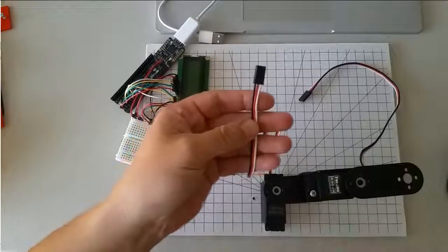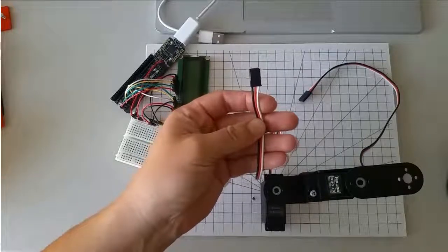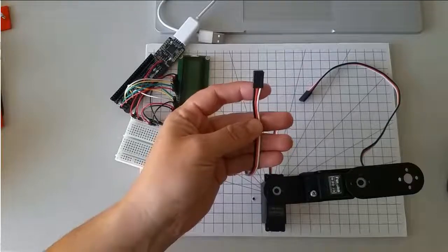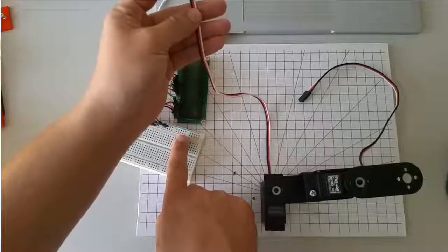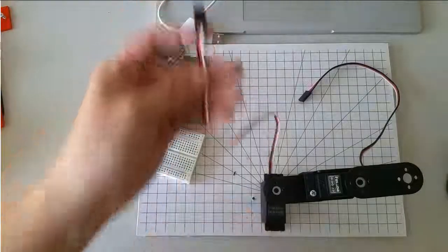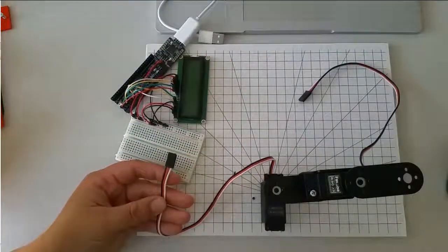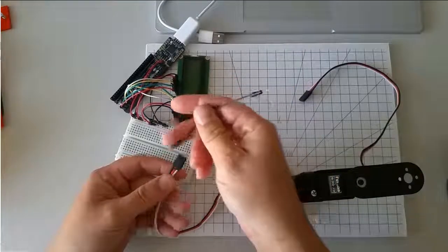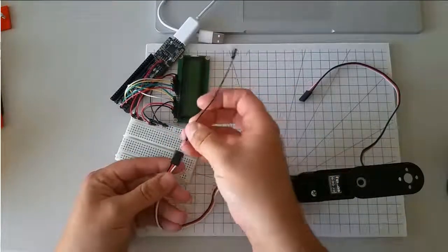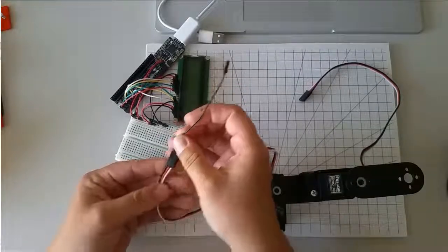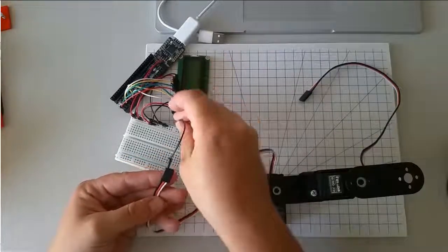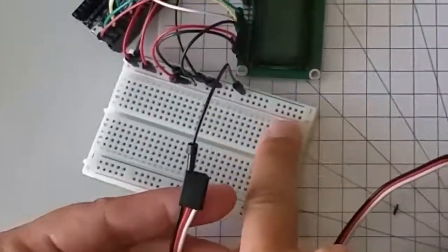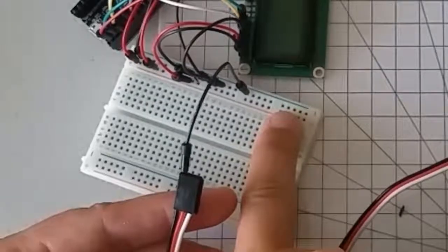Your RC servos each have 3 wires: a black wire, a red wire, and a white wire. The red wire should be plugged into the power rail, and the black wire should be plugged into the ground rail. Use some of your male jumper wires to do this. I'll take this wire and plug it into the black wire of the servo, and then plug the other end into the ground rail that we set up on the solderless breadboard previously.